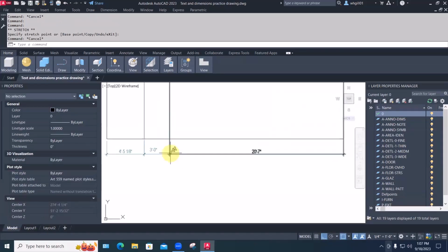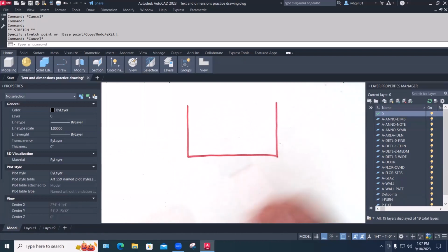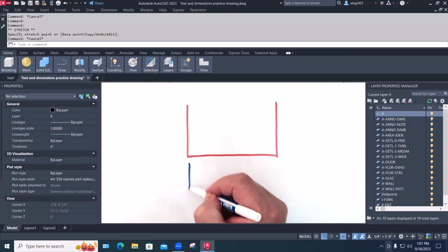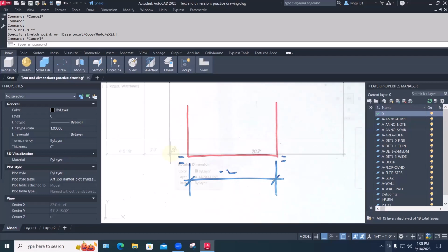We really like to have a gap between the dimensioned object, just to keep clear what's a dimension and what's the thing it's dimensioning. If we have the thing being dimensioned, we really like to have the dimension lines held off a bit from that. You can set how big this gap is, but our definition points are still here and here, invisible, but there's that little space there just to say this is the dimension, even if they have the same line weight and stuff, and this is the thing.